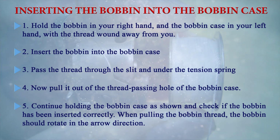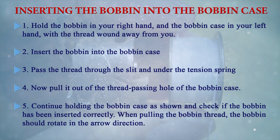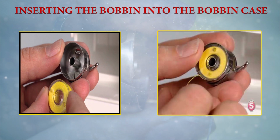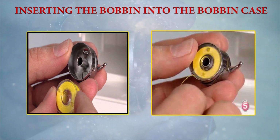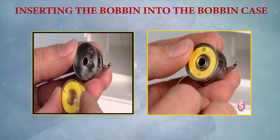When you put the bobbin into the bobbin case, just check whether it is not coming out from the case. And when pulling the bobbin thread, the bobbin should rotate in the arrow direction. So it should be rotating on that case. As you can see in the picture, the thread has been wrapped on the bobbin and it is inserted in the bobbin case, and the thread is pulled out from the slit on the bobbin case. This is how we prepare the bobbin and bobbin case.